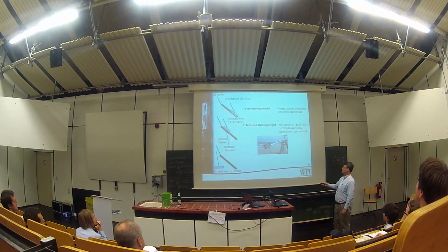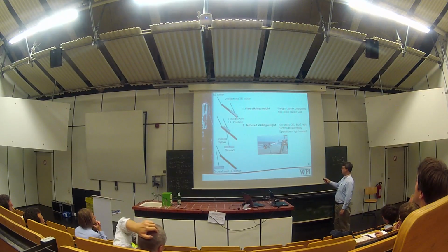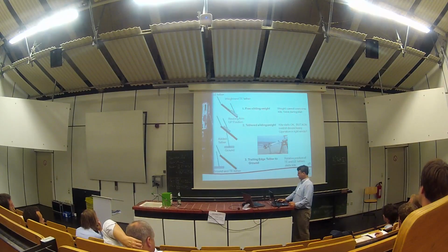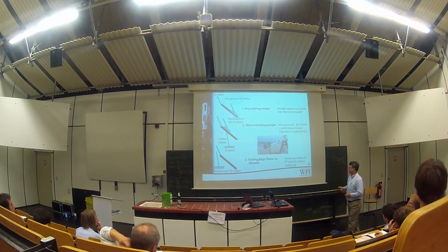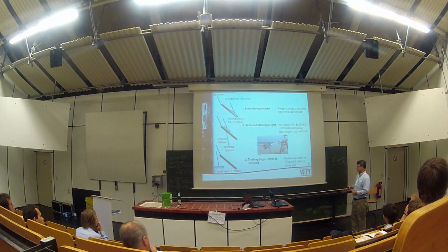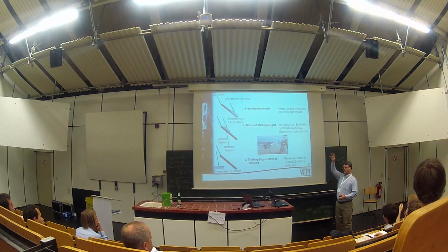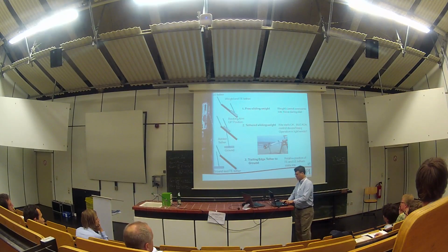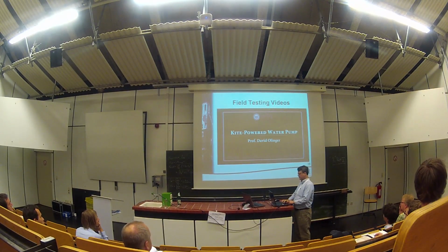We noticed that once you look at this design for a while, notice the trailing edge tether, it really does come down to the ground. It just goes through that weight. Well, why not then attach the trailing edge tether, that would be this one, directly to the ground, and get rid of the sliding weight and all of this. And that's what we're currently studying here, the relative position of the trailing and leading edge tether to stall the kite. When the arm goes up, you're effectively lengthening or pulling on the trailing edge to stall the kite. All right, so design 2 and design 3 are both possible.